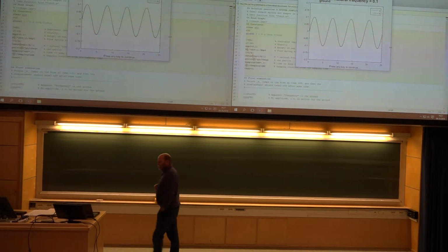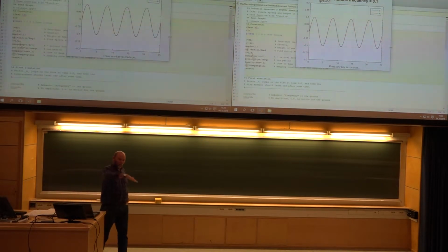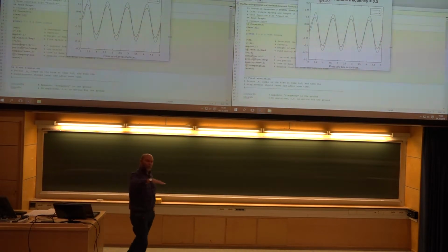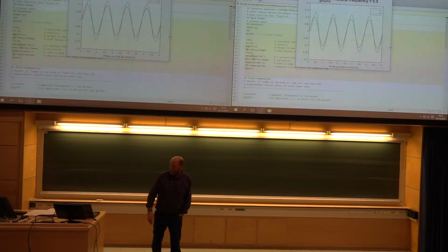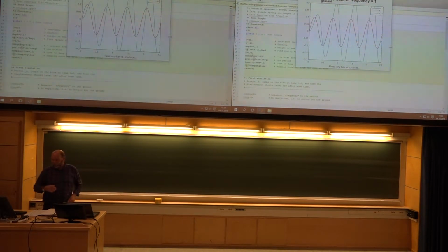And now he starts to bike over sinusoidal ground. Here the frequency is very low, meaning he hardly cares about the waves. He just follows the ground perfectly, so the waves are very, very long. If the waves are shorter, then you fly a little bit up and you go a little bit down in the valleys. And when you hit your eigenfrequency, then of course the system breaks down. It explodes. Here the damper is not strong enough to handle it, so it will really break.